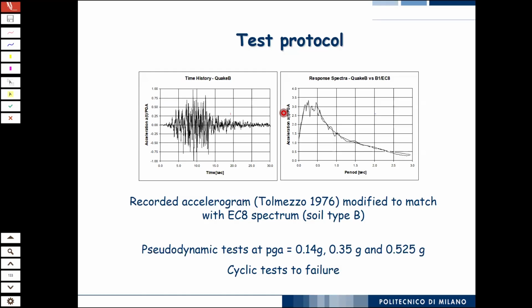The spectrum is what we use in the design codes to design for earthquake, and is actually a diagram like this, which gives us, for the period of the structure, what is the acceleration that we can expect. Okay. Well, the interesting thing, as I was repeatedly saying in these days, is that precast structures generally fall in this region here. And so you see, with respect to the peak, you have a significant lowering.